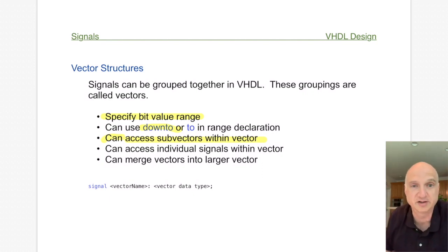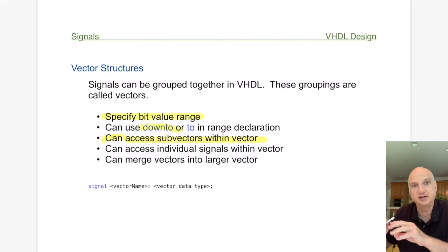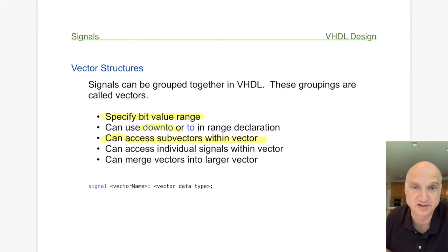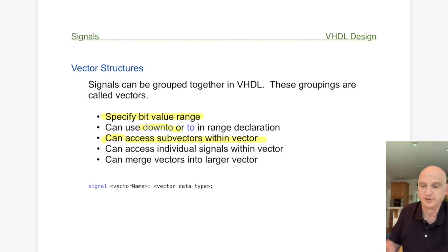You can take a look at the least significant bit, for instance. If you're trying to detect, say, a data value, let's pretend that the data bus represents some sort of numeric value, and you want to find out if the numeric value is even or odd. Well, we would look at bit 0 for that. So you can peel off bit 0 from the bus and feed it into some other logic and use that to decide whether it's an even or an odd number. The same with signed numbers. You can use sign bits and such the same exact way.